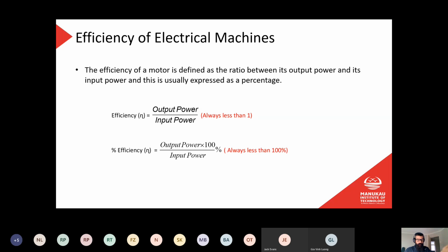Then that cool gas goes back outside, grabs more heat, comes back in and releases that heat. So the reason that we get a greater efficiency is we're not actually burning electrical energy. It's not more efficient, like we're not creating new energy. All we're doing is using electrical energy to power a compressor, and that compressor is what moves the gas inside to outside. The gas is doing the work of grabbing heat from outside and moving it to the inside.